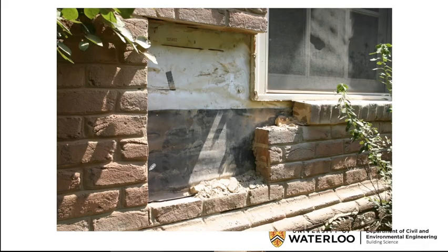Yeah. It looks like there's no flashing under the window. They just made it so that the bricks kind of are forced underneath that windowsill. Yeah, and actually, by the way, it's the same on the jamb. Those are wooden windows, and the wood is directly in contact with brick windowsills. So water will run off the window and soak into the brick, and then it wicks into the windows, which then will rot. And guess what? They do.